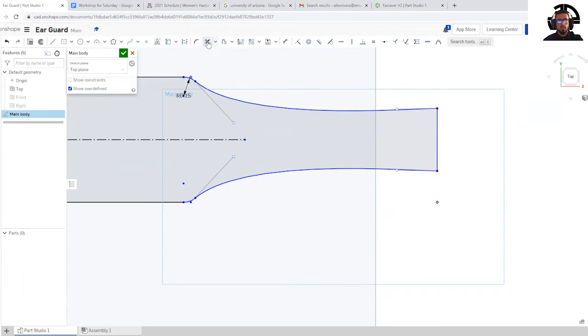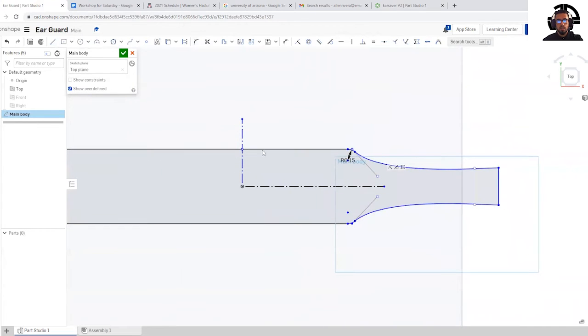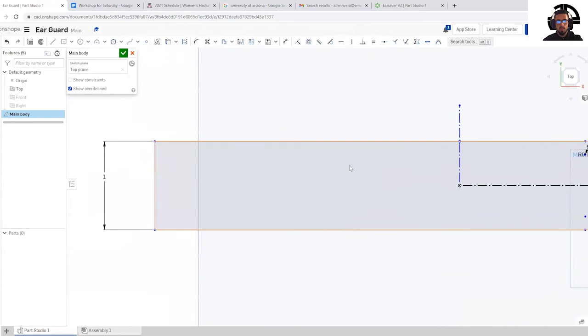I will unclick out of trim or use the hotkey M, and I will click on that dot and delete it because it is no longer necessary. And now we have half of the mask. So now what we want to do is we want to have the same happen for over here on this left side, on this left half of the object.